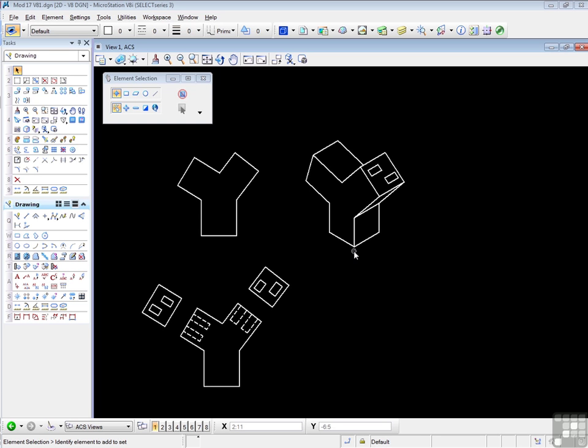ACSs allow you to quickly change the compass orientation in both 2D and 3D space, and equally important, to save the ACSs for future use. The ACS system provides an efficient method of storing different coordinate orientations together with different origin locations. An ACS is a coordinate system, which is the orientation of the X, Y, and Z axes, that differs from the design plane or world view coordinate systems.